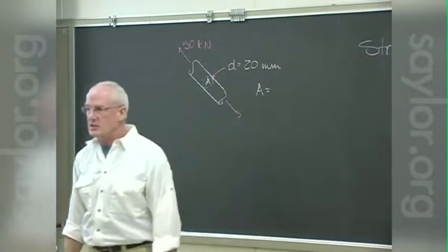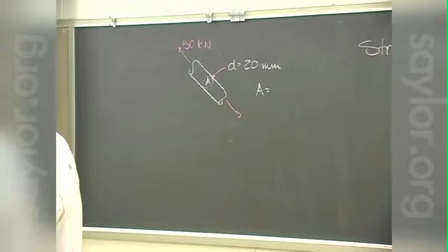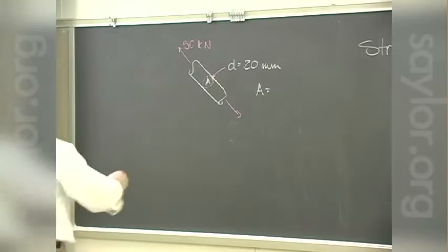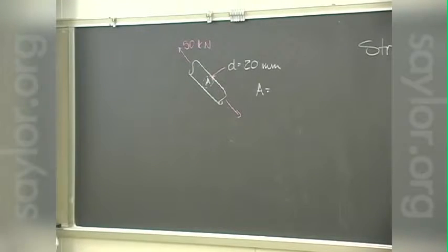So it has a cross-sectional area of, how do you figure out the area? We're assuming that's a circular piece. You can tell that from the type of shape that the draftsman put in. That indicates a circular piece. Same kind of thing I did here on the ends of my piece. That's a common engineering notation to indicate a circular cross-section.